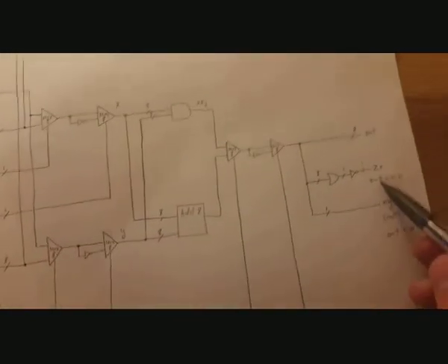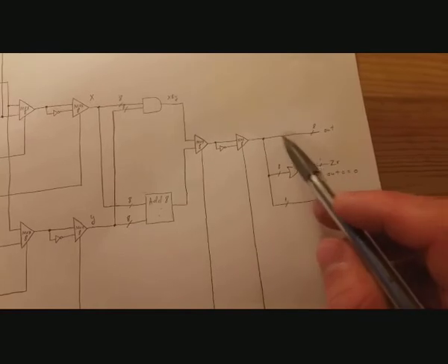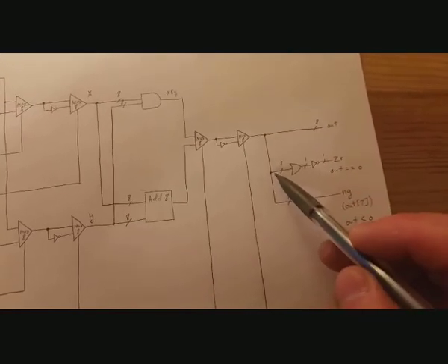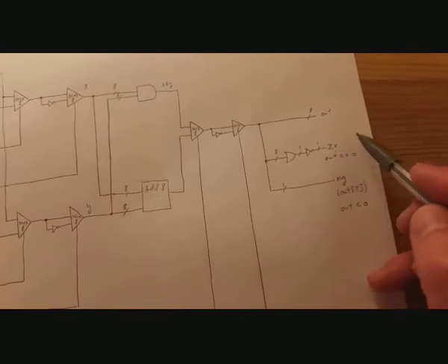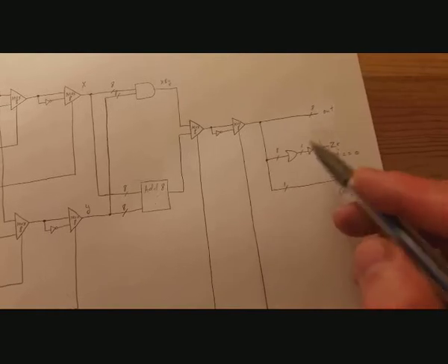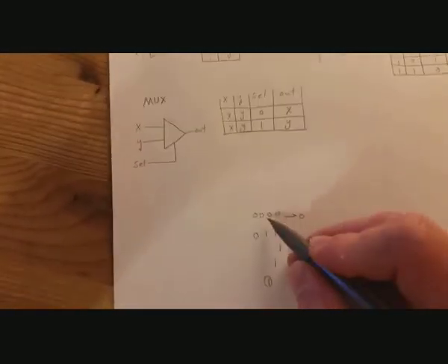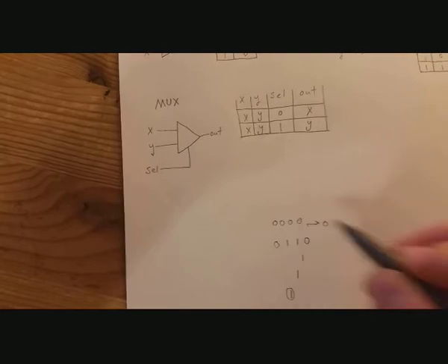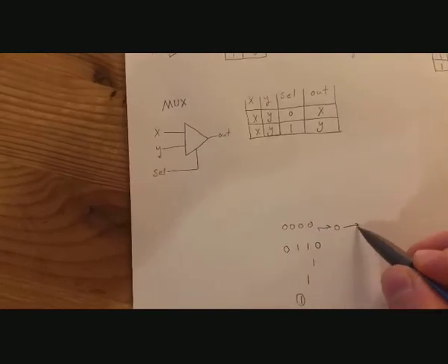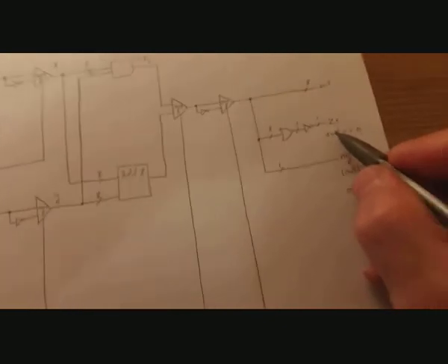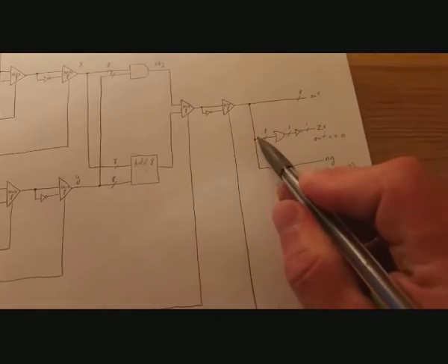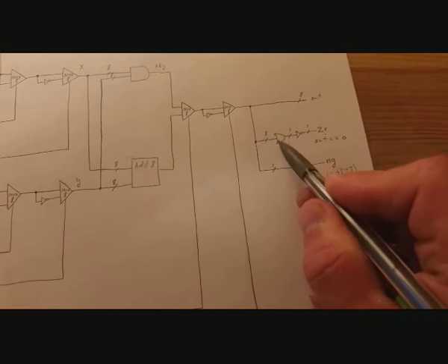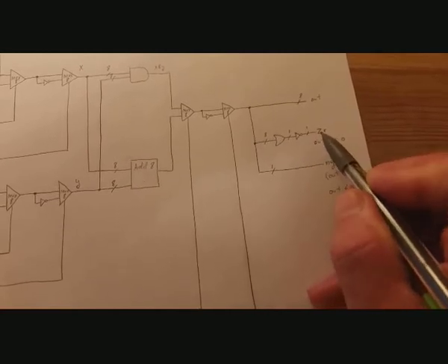So basically, if we want to know the output is 0, we can just go through every one of these wires and OR them all together. And just because we want our control bits to be 1 if something's true, we can just flip that, right? So if we OR all these and we get a 0, well, let's go ahead and flip that to be a 1 because we want this ZR to be 1, meaning yes, it's true, the thing is 0. You could do it either way. That's just the way they do it. So I take every one of these wires, OR them all, and then flip that bit.